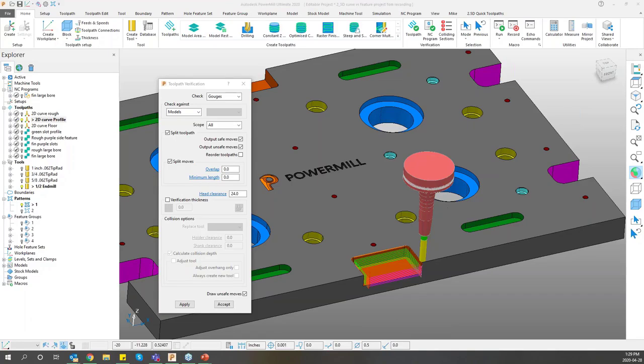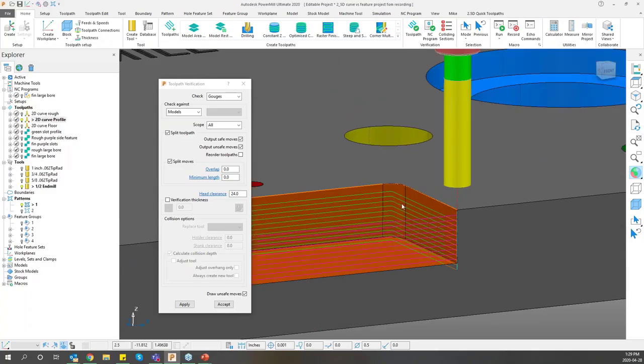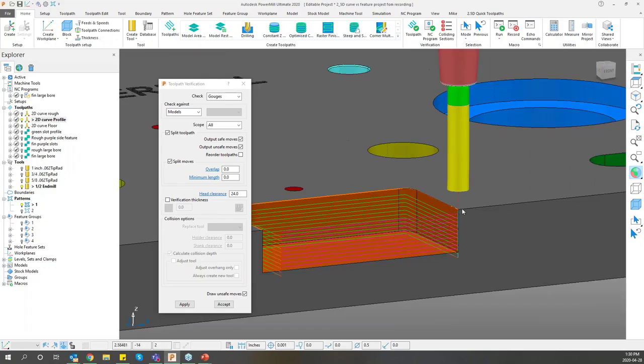When you pick your pattern, does it matter if you use the top of the feature or the face of the feature? Like, does it matter if you use the floor, the top, anywhere on the model? No, as far as the Z value is concerned, you're going to be driving that with the numbers inside PowerMill. If you remember, we picked the lower limit for the lower limit, and then it can be the top of the block if you want. I'm going to be honest, I've always used it that way, but my pattern I usually have above, and I machine down from it.